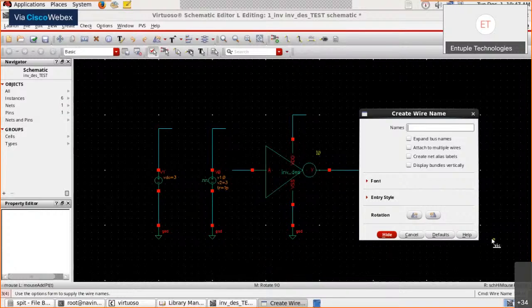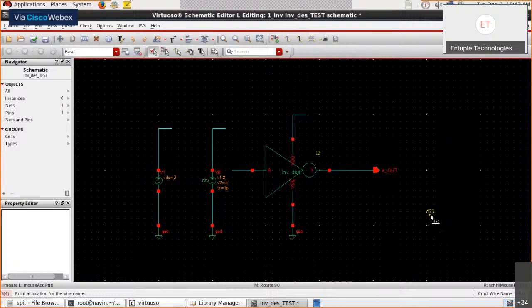So I'll label the nets. VDD is what you need, and begin. Because we need to have the labels in both the places, so then it will get connected. So VDD once over here and once over here, and then begin. Fine, so this is done. This establishes soft connection between the terminals. So I'll check and save the design.